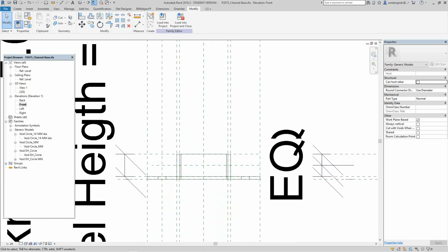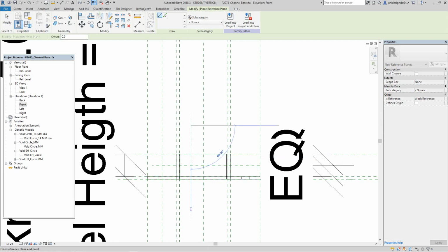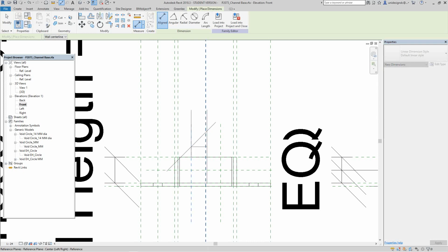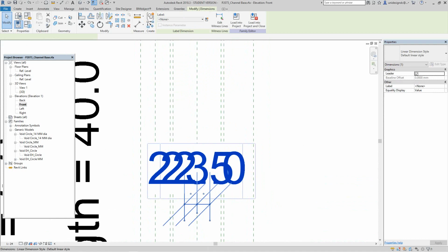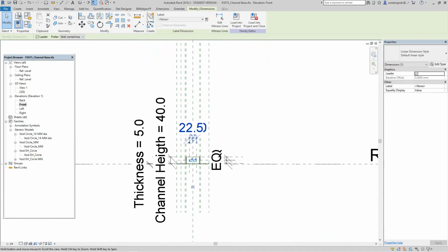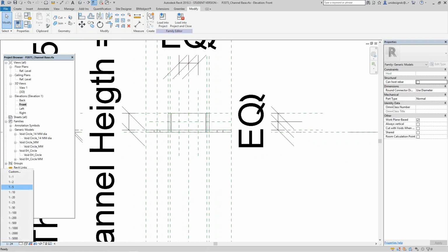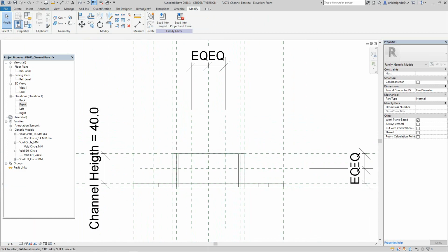So now we had 2 more holes back here. We got our center point. And let's just go in here, right click, create similar. Place one here. Place another one there. Let's go equality about the center. Okay, make this scale a little bigger so we can see what's going on. So now we got all our hole centers.